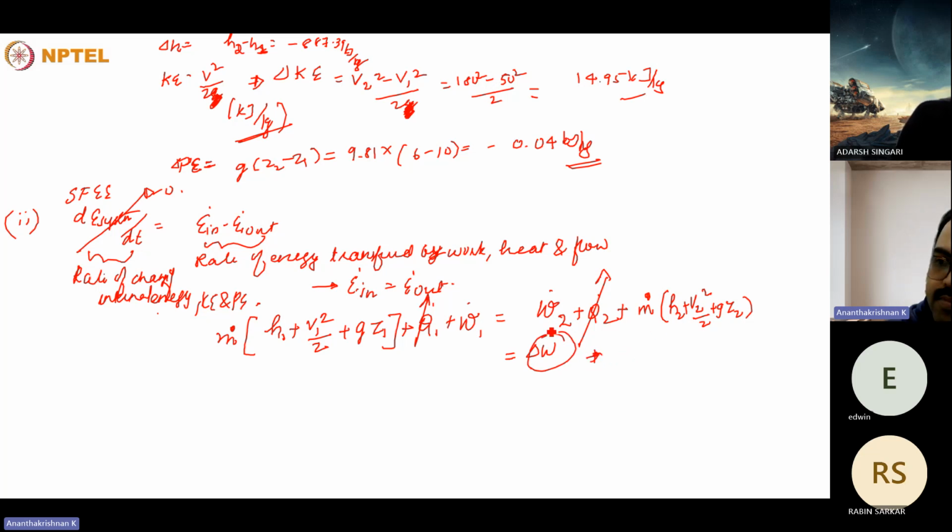And for that, we take this particular quantity to the left-hand side, assuming there is no loss of the mass in the process, assuming that the continuity remains the same. So m dot 1 equal to m dot 2, there are no branches or no loss of fluid in this process.